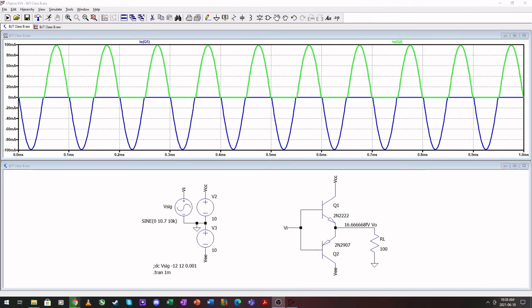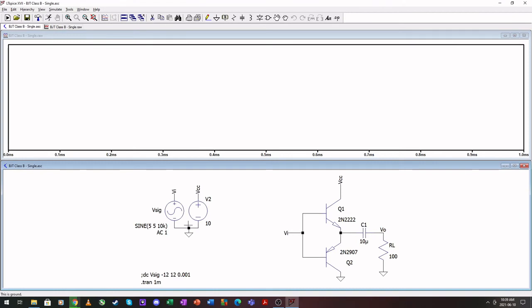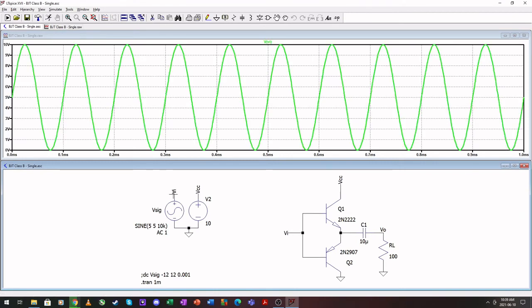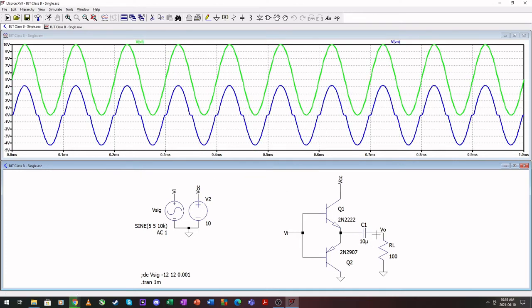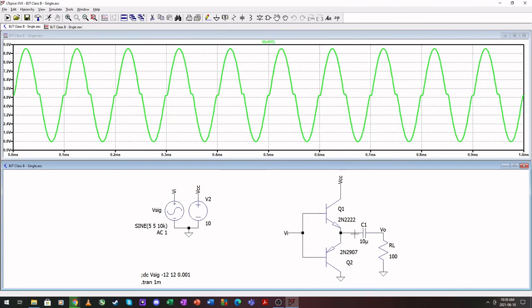Okay, let's open our single rail and then our op-amp configuration. Right, here I have a single rail application. I apply a 5V DC offset and half the rail at the input. So this is our input signal. It is with a 5V DC offset, plus minus 10 volts, and there is our output with DC removed with this capacitor right here.